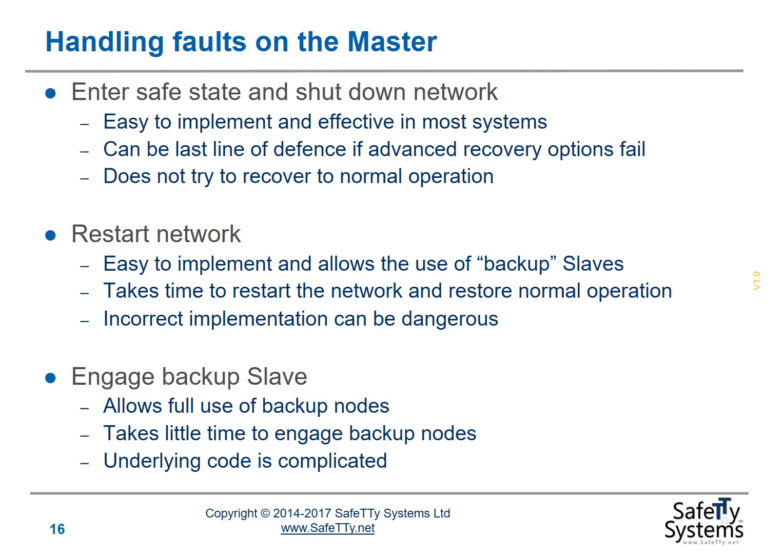And if the master thinks that one of the slaves is faulty, the master stops sending out any tick messages on the bus. All of the slaves detect that no tick messages have been sent. All of the slave nodes will enter a fail-safe state, and the whole network will be shut down.